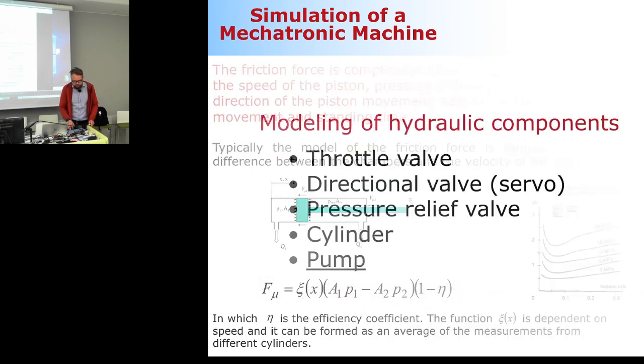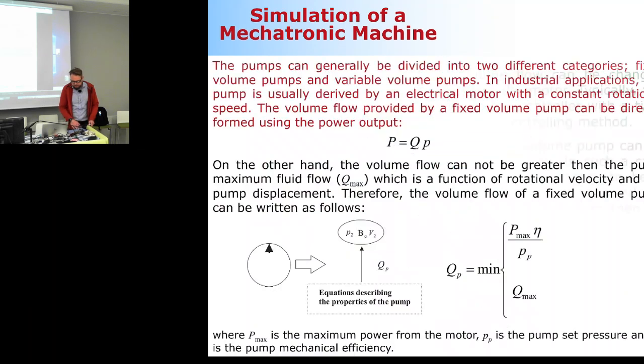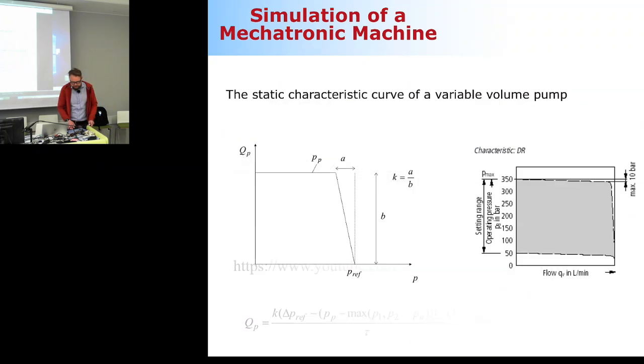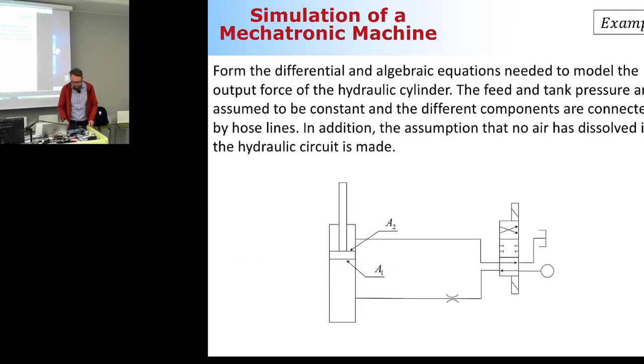So this is now PowerPoint, so I'm not able to write anything on the slides, but at least you can see the hydraulic circuit that I would like to introduce here. Here's a quite simple hydraulic circuit. I have a direction valve with 3 different operation phases, connecting 4 ports, and a constant pressure source, which is this round symbol here. Then the direction valve is connected to a throttle valve, the one that is here.